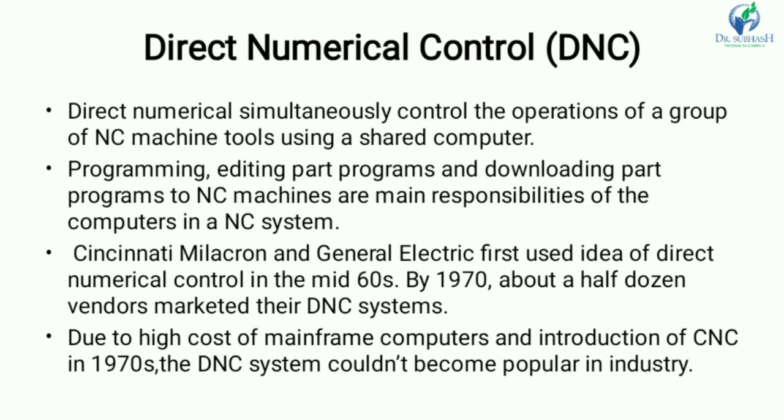Then next is direct numerical control, known as DNC. Direct numerical control simultaneously controls the operations of a group of NC machine tools using a shared computer. Programming, editing part programs and downloading part programs to NC machines are the main responsibilities of the computer in an NC system.